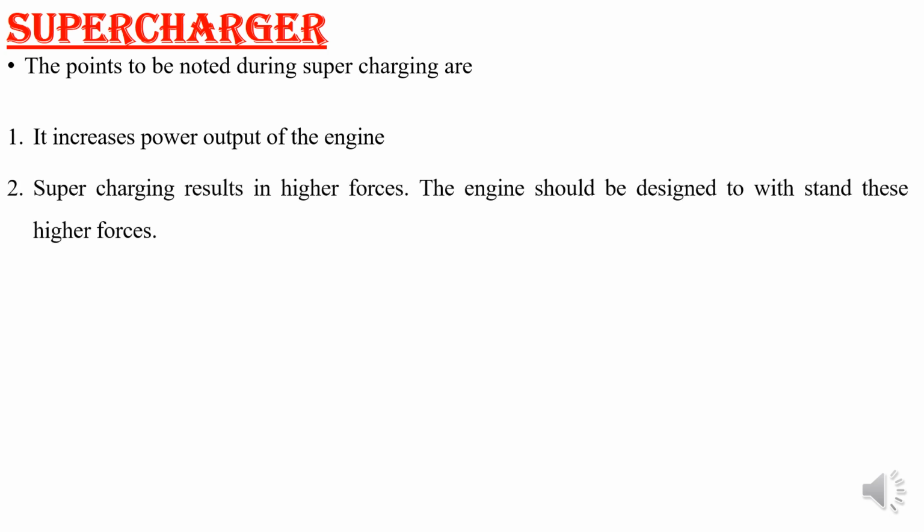Supercharging results in higher forces, because air density is more and the pressure created inside the cylinder is more. Combustion pressure really increases because more fuel can be burned along with the air, more air. So air quantity increased, combustion pressure will increase, hence the engine should be designed to stand this kind of forces, especially thermal loads, depending upon supercharging pressure ratios. So the engine should bear that load.